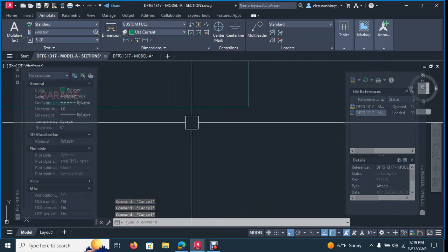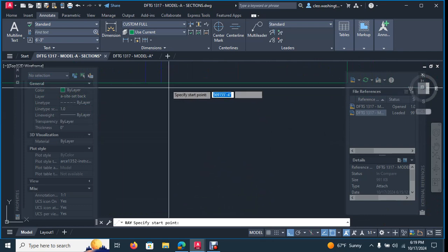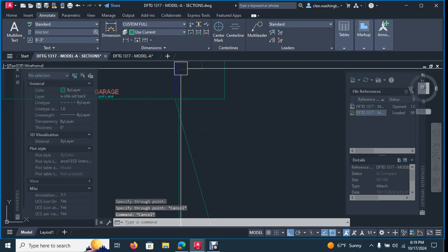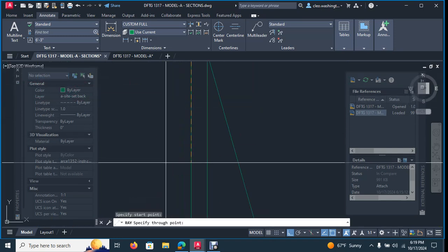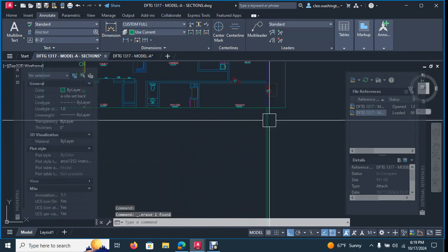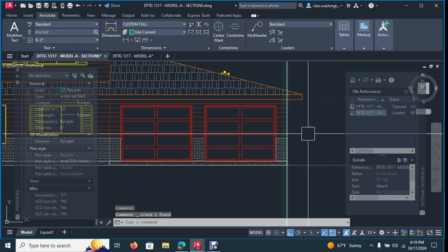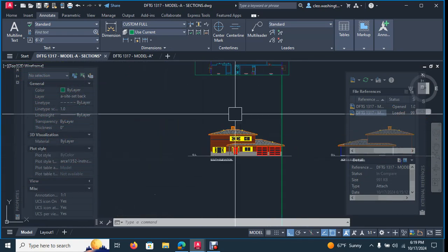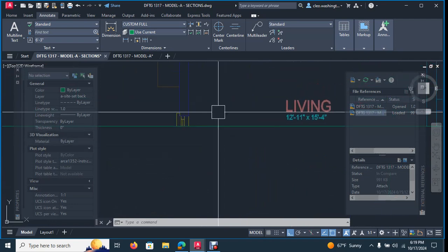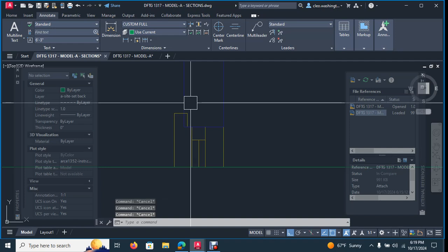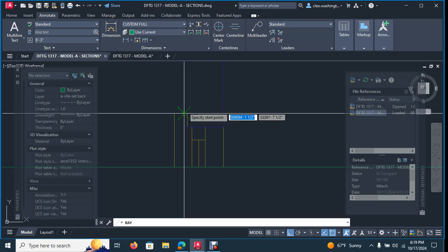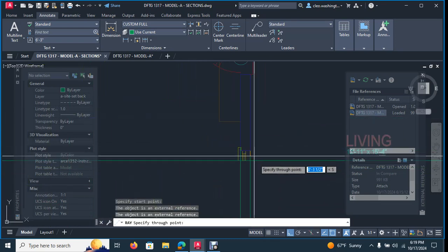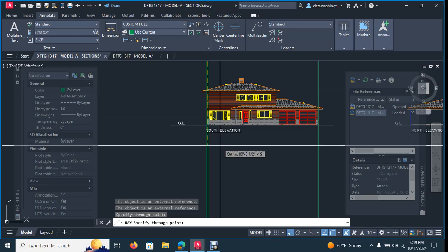So on this side, when you project the lines down, RAY, this should be an exterior wall, okay? Let's hit escape to get out of that. And that's going to show you where your exterior wall is. So we'll go ahead and start cleaning some of this stuff out and start putting in exterior walls, okay? Here's another exterior wall, but this guy's through a window. So you want to type in RAY and project this guy down. And project this guy down. Don't project the window down. We're going to draw that in, okay?